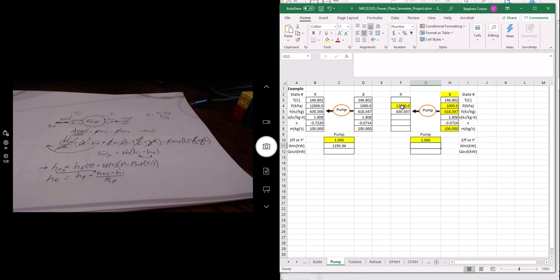Okay, so now I have pressure and enthalpy, so I can do the same thing I did on the other side, equals water, pressure and enthalpy given, temperature, and the pressure is here, the enthalpy is here. Now I get the temperature. The entropy can be found the same way. Pressure and enthalpy, and entropy, specify those two cells.